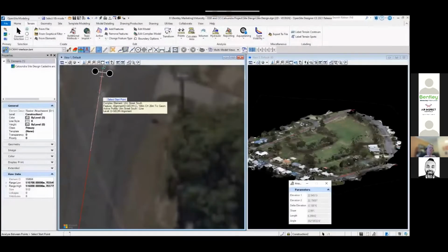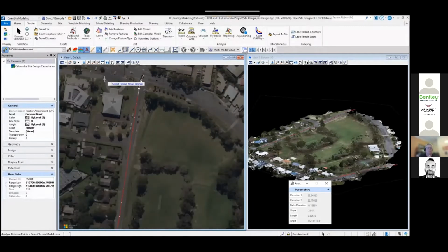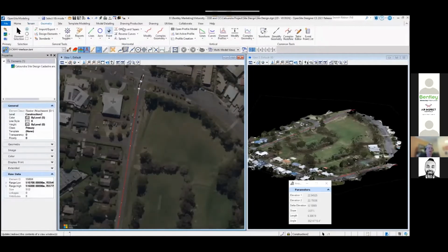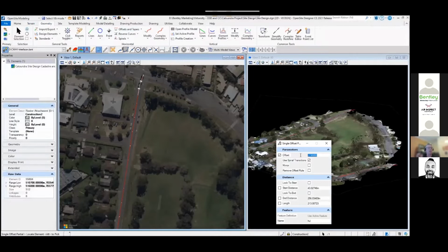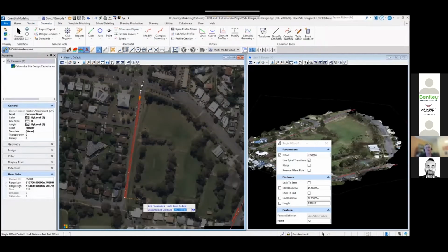It was also decided that we would offset 2.5 meters from the center line to determine a cut line from Ulm Street. So from the Ulm Street center line out 2.5 meters, anything beyond that, heading east towards the park, we're going to do some full reconstruction of that portion of Ulm Street.